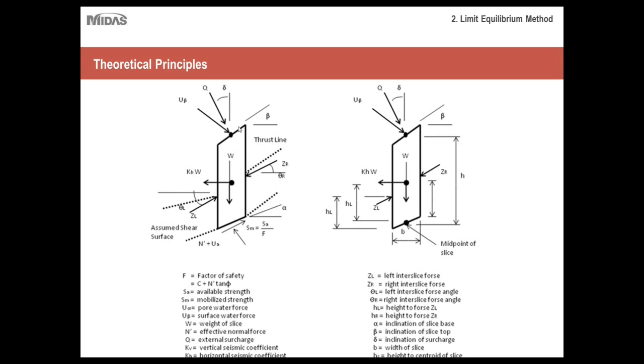As you can imagine, to do this by hand would have been a very long and iterative process, because you have to calculate these forces for each and every single slice, and then take those calculated forces and apply them to a factor of safety equation, which I'll show you momentarily. So hopefully this gives you a better appreciation of what these programs do for you, as they take a process that was very long and iterative and compute it automatically, so that you can focus more on the input and the results, as opposed to the actual process of doing the calculations.